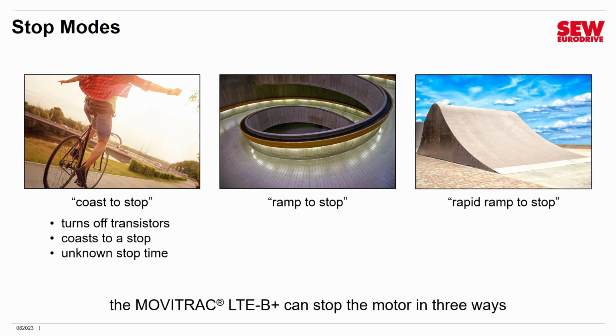So for this reason, the stop time isn't known. It's dependent on a lot of different factors, such as the size of the load, the friction in the system, and the configuration of the application. Now, if you've got a brake on your motor, you can bring it to a stop pretty quickly because the brake will apply as soon as all this happens, and the load will probably stop very rapidly. But if you don't have a brake on the motor, it's very application dependent. So be aware of this.